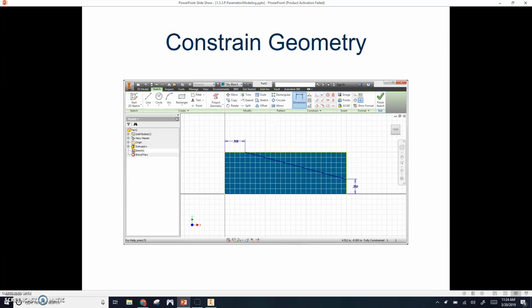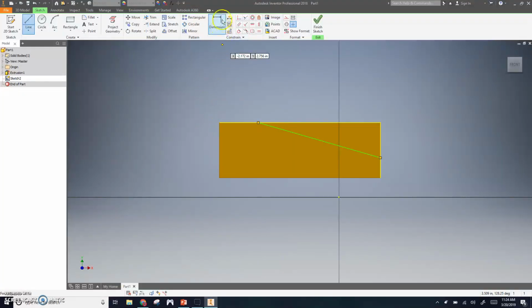It should be 1/2 inch from the left side and 0.35 inches from the bottom. Let's go back to our dimensions. Inventor. We're going to click on the dimension constraint. So click on dimension up top. We're going to click on the left side of our part to the left endpoint of our line. So click on the endpoint of that line. Go up. Click one more time. And we're going to type in 0.5 for 1/2 inch. 0.5. Can you say 0.5, Alana?